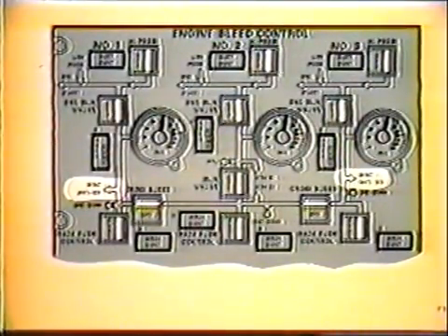The points at which pneumatic pressure is available for wing anti-ice are depicted here on the pneumatic panel. Note that the left and right ends of the crossbleed manifold must be pressurized for anti-icing to be used on both wings. Normally, the crossbleed valves are open, and all 3 engines are connected to the crossbleed manifold. When wing anti-ice is selected on, all high-pressure valves may open, depending upon engine power setting to provide sufficient temperature.